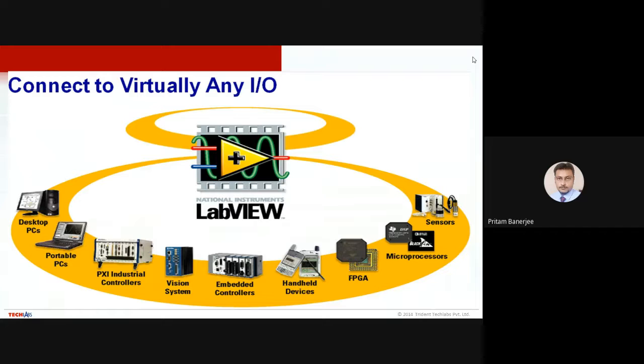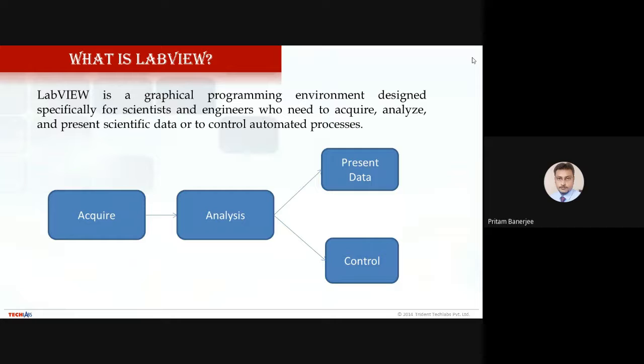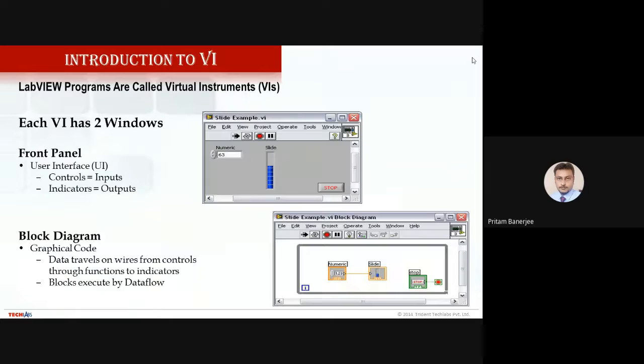So you could be able to connect virtually with any of the input output devices. So basically LabVIEW is for acquiring the signal, analyzing the signal, and presenting the signal, as well as controlling the signals. As I have already mentioned, it has two panels: one is the front panel, another is the back panel, the block diagram.